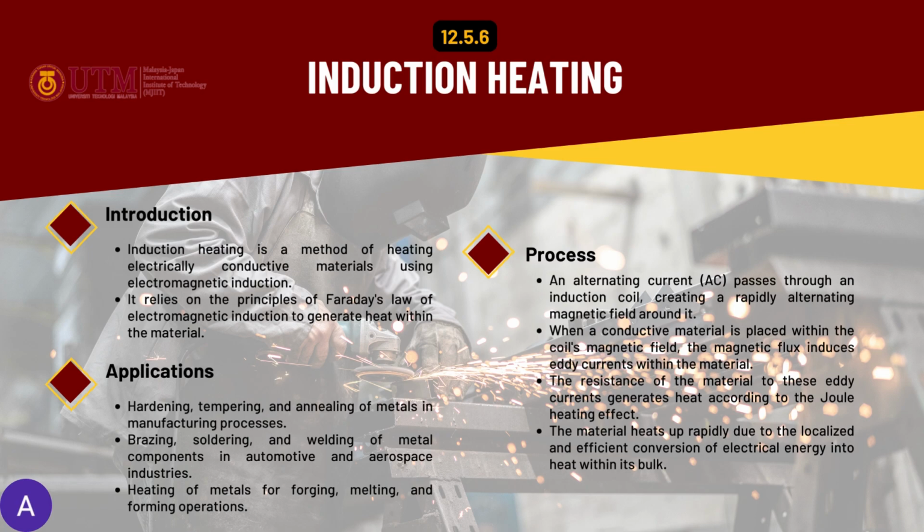The working process for induction heating is: an AC current passes through an induction coil, creating a rapidly alternating magnetic field around it. Then, when a conductive material is placed within the coil's magnetic field, the magnetic flux induces current within the material, and the resistance of the material to this eddy current generates heat according to the Joule heating effect. And then the material heats up rapidly due to the localized and efficient conversion of electrical energy into heat within its bulk.